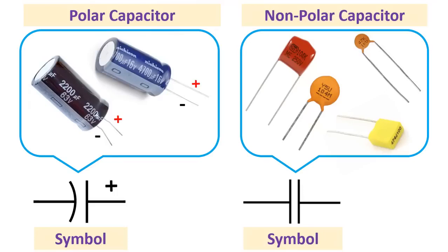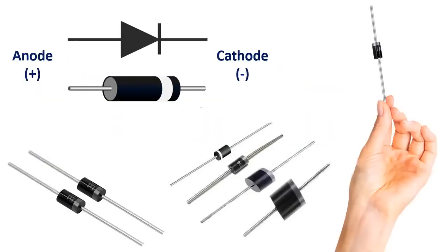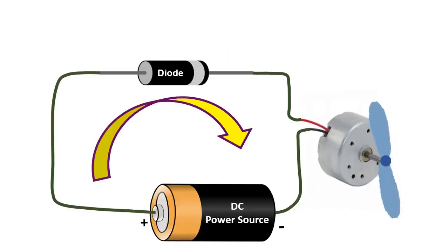Electrolytic capacitors have the value written on them, typically represented in microfarads. Step 6. Diodes. Diodes are components which are polarized. They only allow electrical current to pass through them in one direction. This is useful in that it can be placed in a circuit to prevent electricity from flowing in the wrong direction. They are represented in a schematic as a line with a triangle pointing at it.